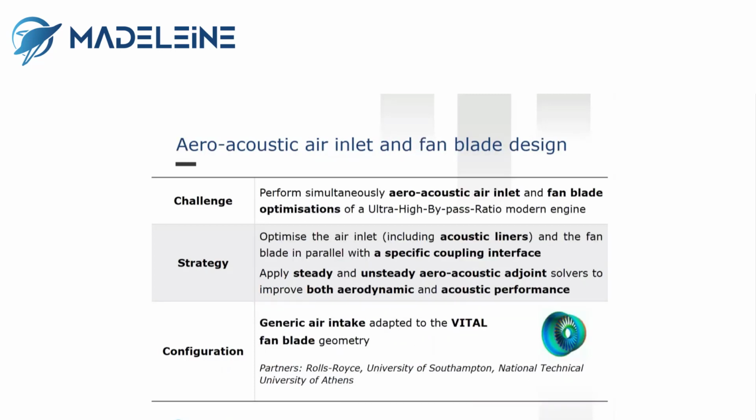And the last test case is aeroacoustic air inlet and fan blade design. Here the challenge was slightly different, as we decided to perform in parallel the design of the air inlet and of the fan blade of this UHBR configuration. Two partners were working, on one side on the air inlet, on the other side on the fan design, and they used a specific approach and specific interface to exchange data and to make this coupled adjoint-based optimization.